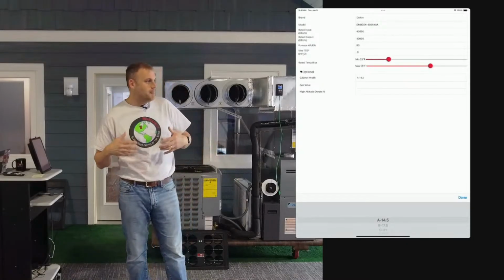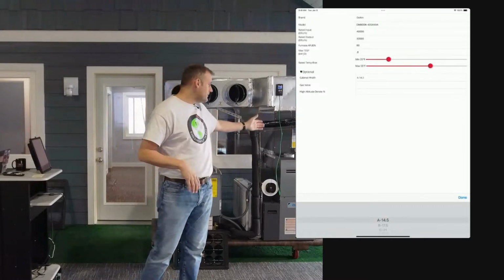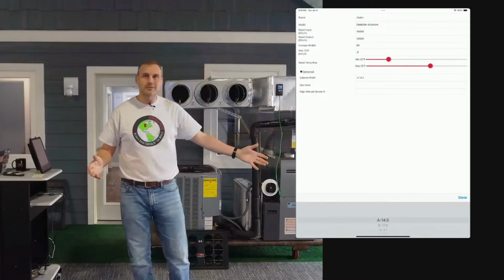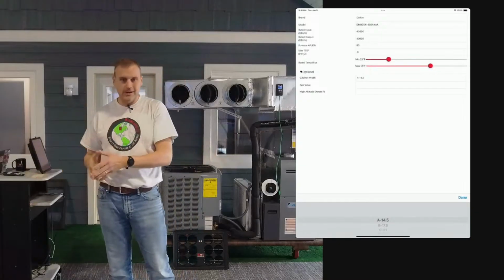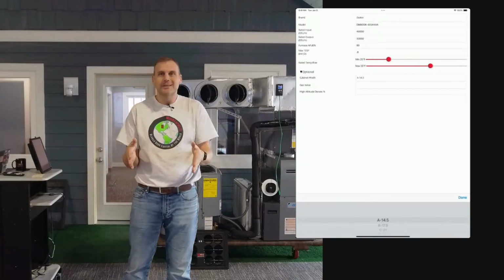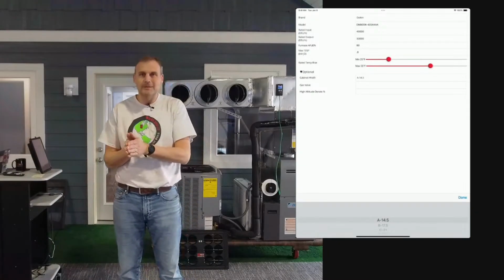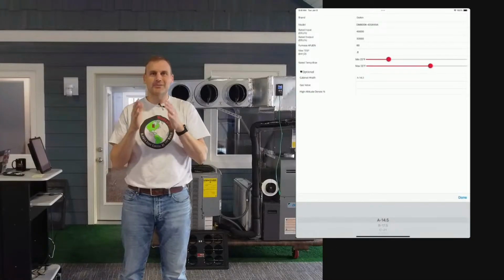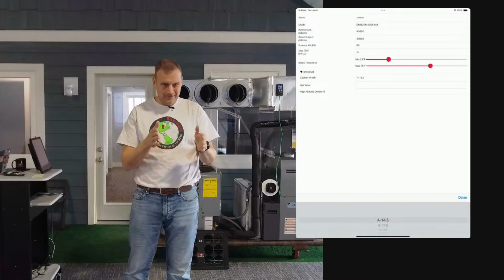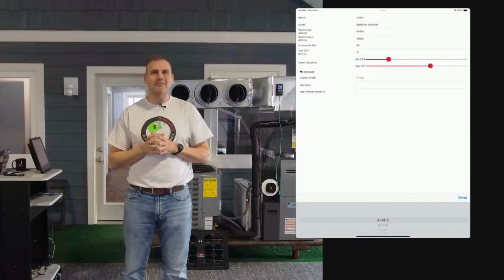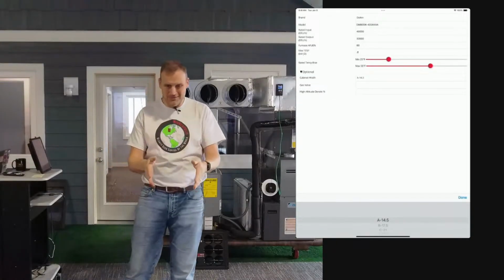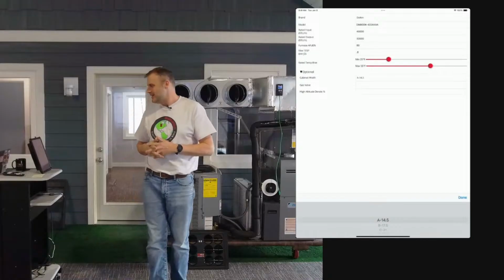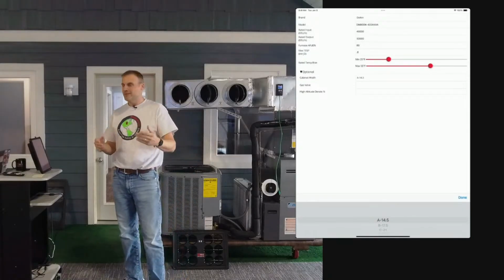If you're in basement country and you have a vertical system, a lot of times there's a water heater right next to it and you're limited on space. There's a wall, there's a furnace, there's the water heater, and you have only so much space. So if you're selecting a piece of equipment, cabinet width is important. So let's say you're trying to pick between 3 and you have 2 14s and 1 17.5. Well, you may want to just eliminate that 17 altogether. Show me the 2 14.5-inch furnaces. That's part of a filtering game to come.